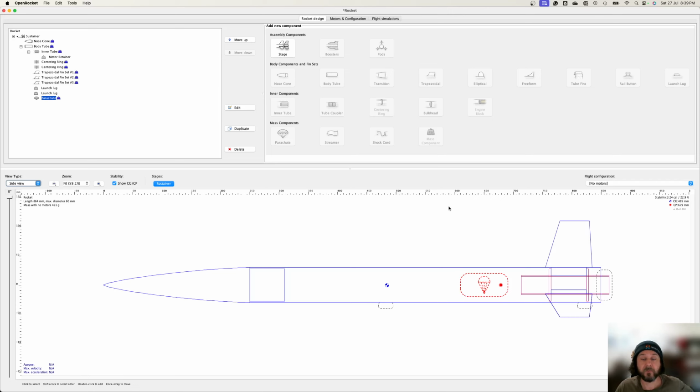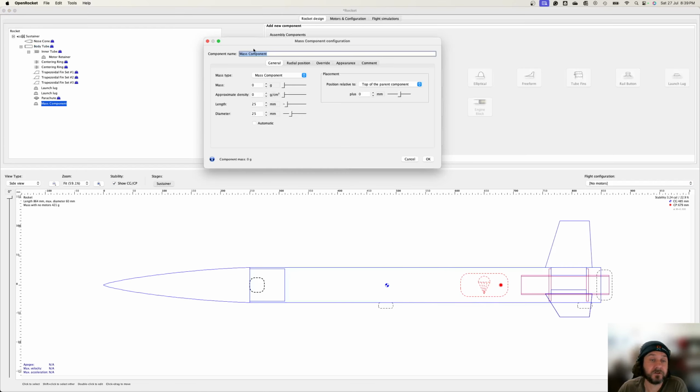Now the parachute is protected because the ejection charge is a hot charge. So it's protected by a Nomex cloth. So I'm going to add here Nomex cloth, and this is really just something that's made out of a material like a firefighter's suit, and we wrap the parachute in it.